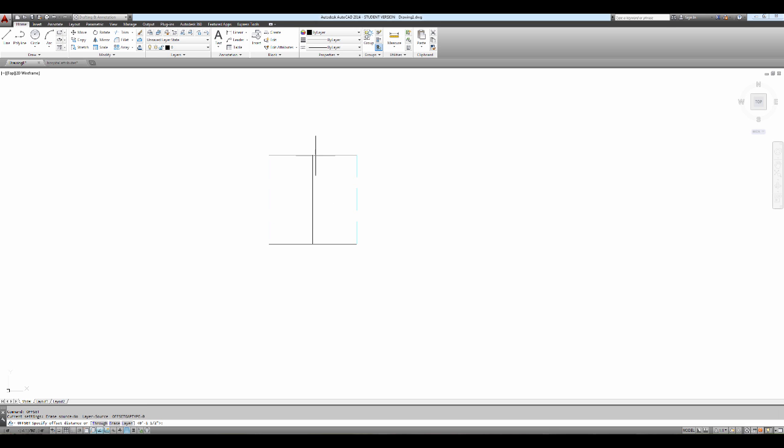So I'm going to just say I want to offset it about this much. Now you can offset, I don't know if you guys know this or not, but when you pick dynamically on your screen, because I don't really know how far I want to offset this, I can just visually click, say here, and then click here and say I want my offset to be that far.